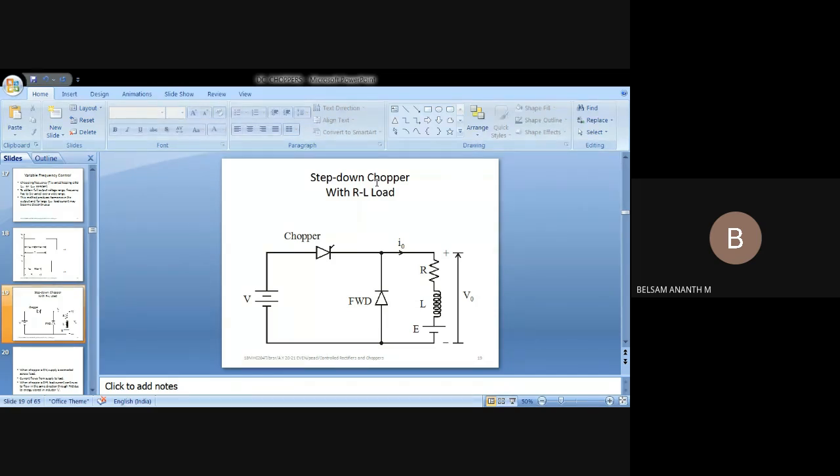So here, the inductor will have an ability to discharge. At one instant, again, you need to have a discharging time. In order to avoid the reverse amount of current which flows through it, a freewheeling diode may be connected here to protect your chopper from the reverse current. Thereby you get your step-down output voltage, which appears across the RL load, or across the output side.